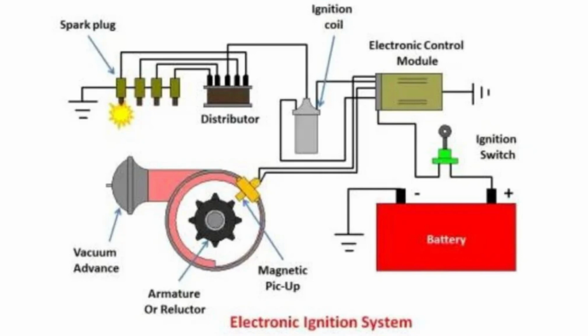In this arrangement, the coil produces 2 sparks per cycle, one to each cylinder. The fuel in the cylinder that is almost finished with its compression stroke is ignited, whereas the spark in its partner, which is almost at the end of its exhaust stroke, has no effect. The wasted spark system is more stable than a single coil system with a distributor and cheaper than direct ignition. When the coils are individually applied per cylinder, they are all kept in a single mounted block with various high-tension terminals. This is called a coil pack. A bad coil pack will result in bad fuel consumption or loss of power.